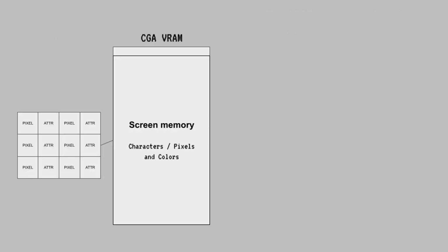Before we come to actually implementing what I was talking about, I want to introduce you to the memory map of the VDC chip and the difference to CGA. I talked about attribute bytes before. On CGA, each character takes up 2 bytes. The first byte contains the character index, the second byte is the attribute index. So both types of data are stored in an interleaved way.